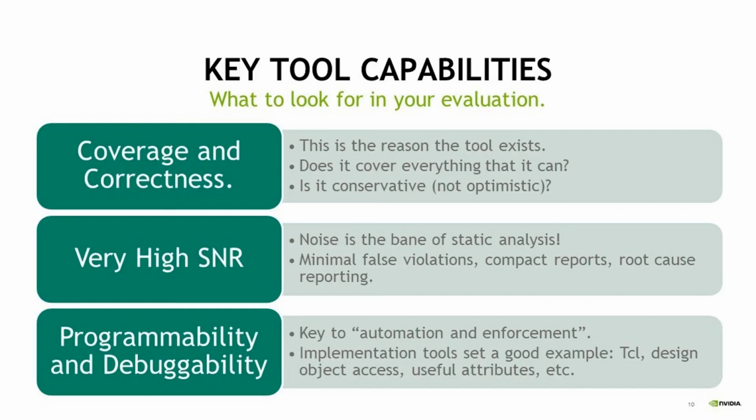If you're evaluating new tools, these are some of the things that differentiate static sign-off or really any EDA tool. Of course, the main thing you're looking for is the coverage and the correctness of the analysis. That's why the tool exists. And you want to make sure that it's catching everything that you're concerned about and that it's not an optimistic tool. It's conservative and it's got to flag everything.